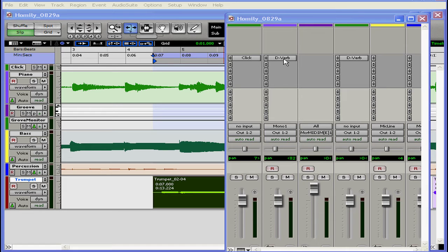There are many kinds of signal processing that are commonly used in audio. They can generally be grouped into two categories, dynamic-based effects and time-based effects. EQ, or equalization, compression, expanders, gates, and limiters. These are effects that change the dynamics or frequency and volume of your audio signal. Normally, you'd use these on inserts rather than sends because you don't typically blend a processed and unprocessed signal together. You're going to need 100% of the audio processed as it plays.